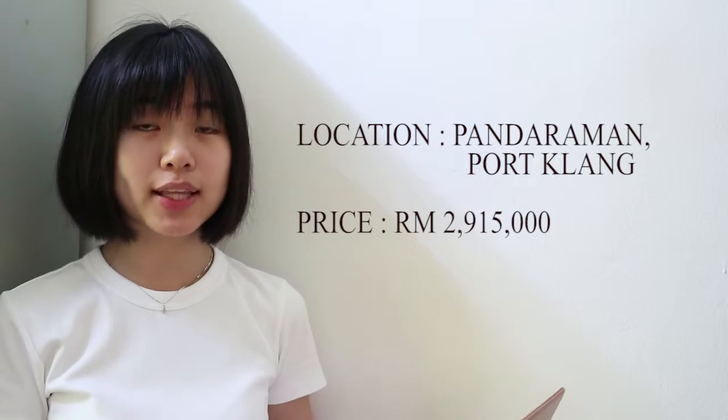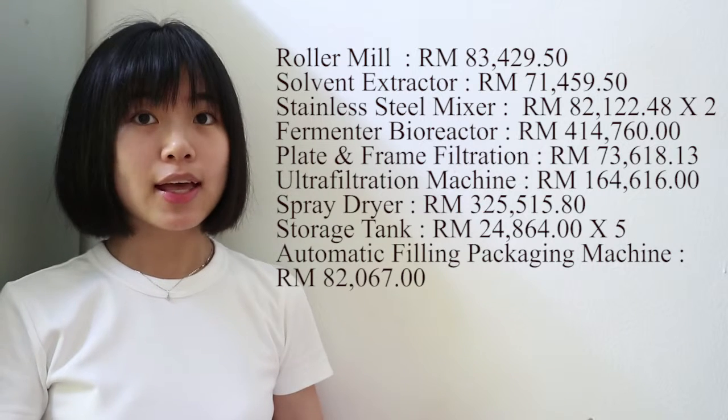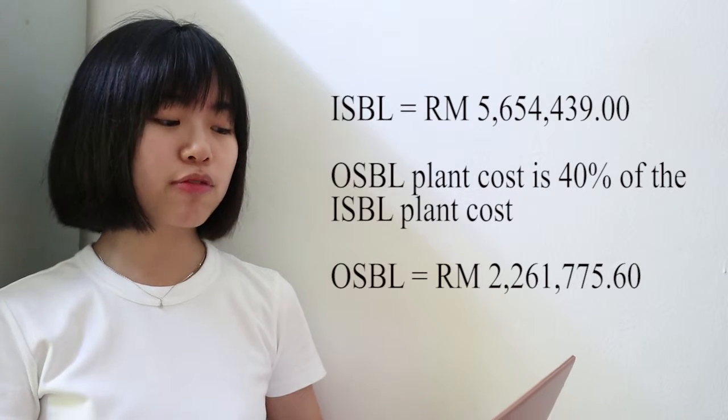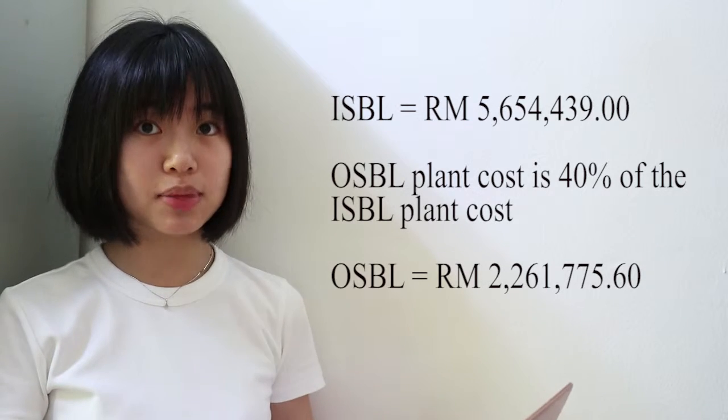So for our task, firstly our land purchasing price is 2.9 million, which is located in Port Klang, Pandamaran. And then next, the list of equipment cost is over here. And then for the cost of ISBL, calculated by multiplying the solid processing plant factor of 3.1, our ISBL will be 5.6 million, and then our OSBL is 2.26 million.